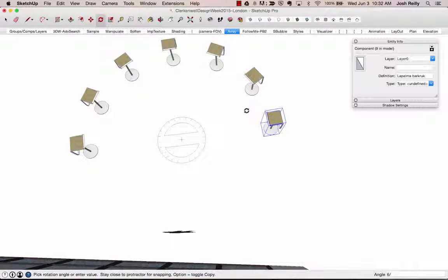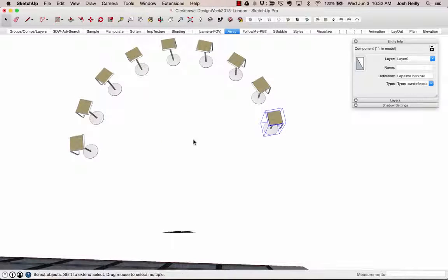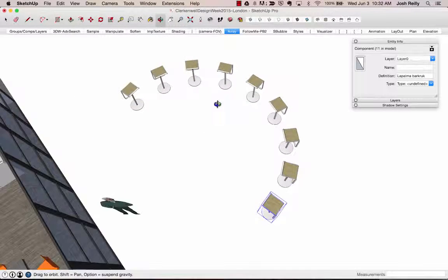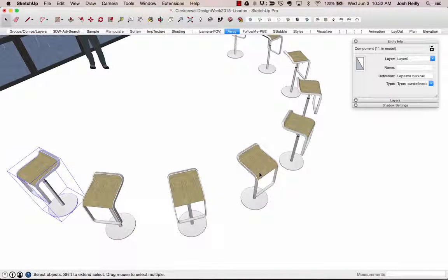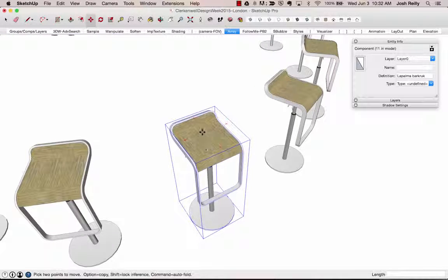And now I'm going to type in, let's say 6, and then the slash key, and then enter. So it's giving me equidistant copies there. It's infilling that space. And if I don't do anything else, I can again change my mind. 12 slash enter. Let's try 8 slash enter. And then these are facing the wrong way, so I could click on the object and go to the move tool. And with this tool, if I hover carefully over the bounding box, you can see that there is the ability to do a quick rotation here as well.